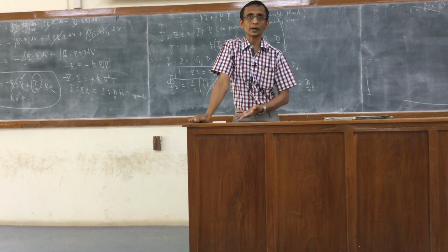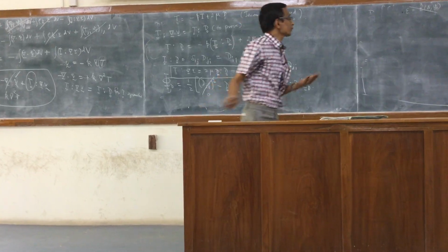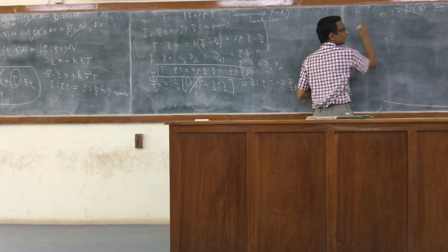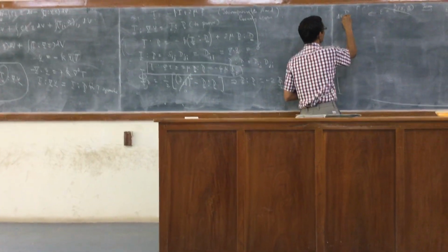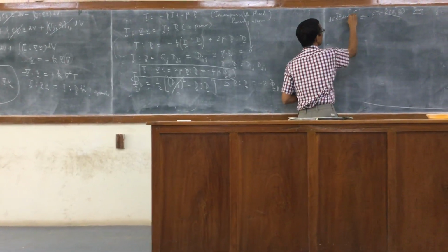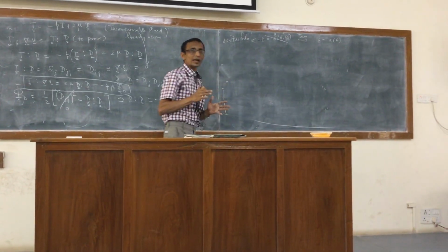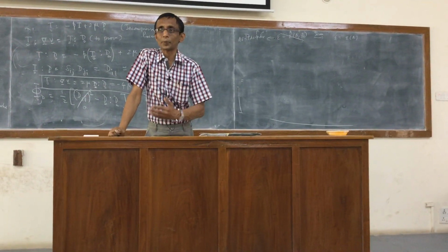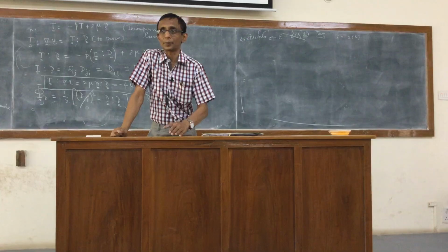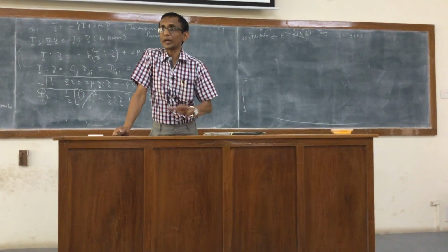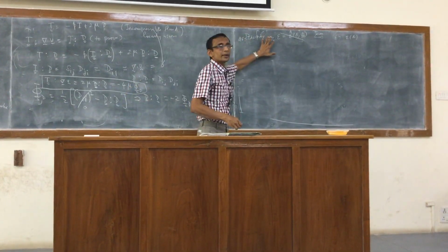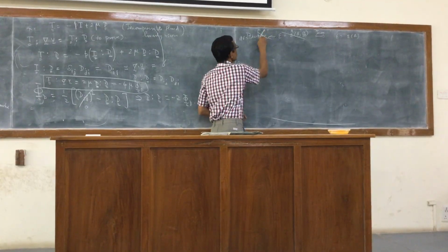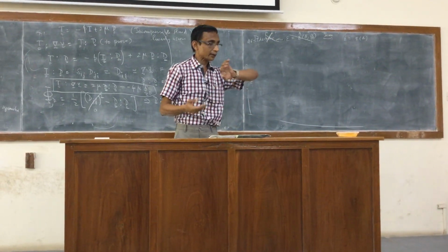If you draw the associated differential relation, the pressure term is not valid for an incompressible fluid, because as we said, the pressure is not a thermodynamic variable, it is a mechanical variable, so it cannot be defined through the internal energy. So this term simply will not be there.